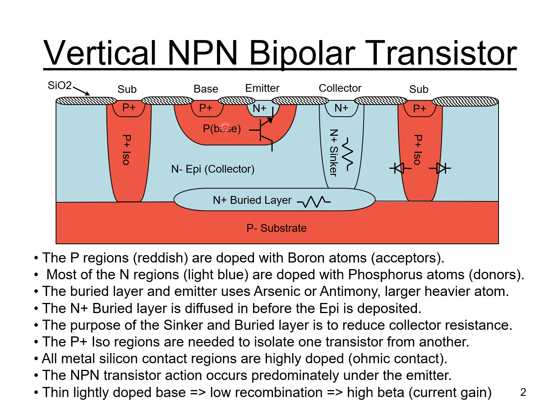So what we are looking for is trying to get high current gain, and current gain of the bipolar is called beta, and beta is defined as the ratio of the collector current to the base current. So the more collector current we get for the less base current, the better. And again, base current is predominantly caused by recombination in the base region.